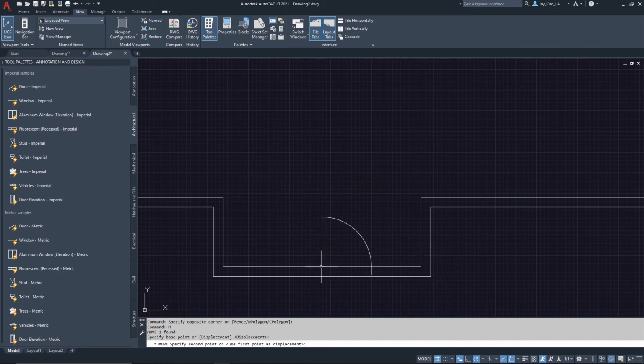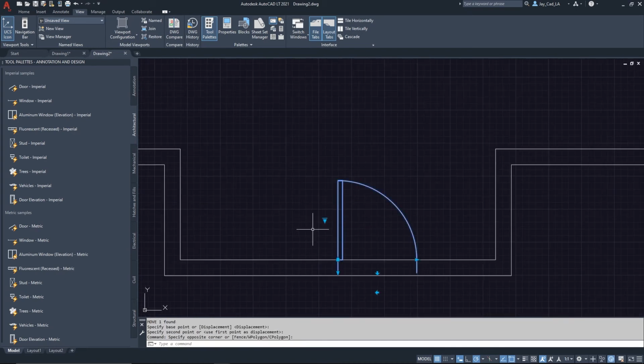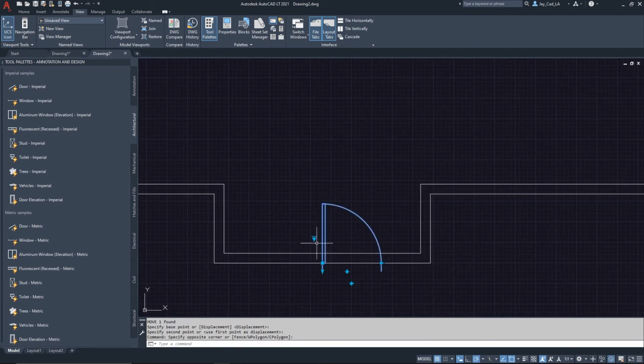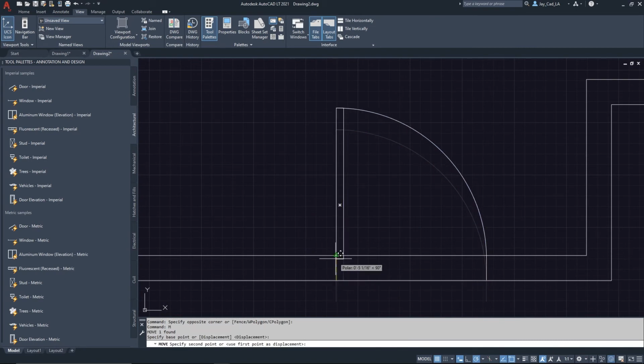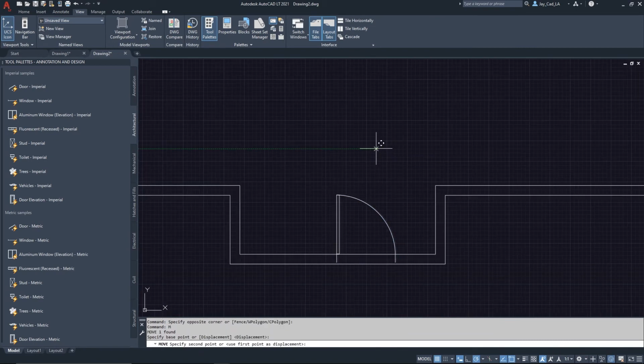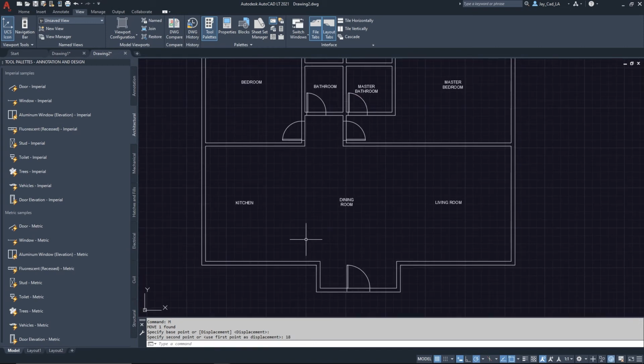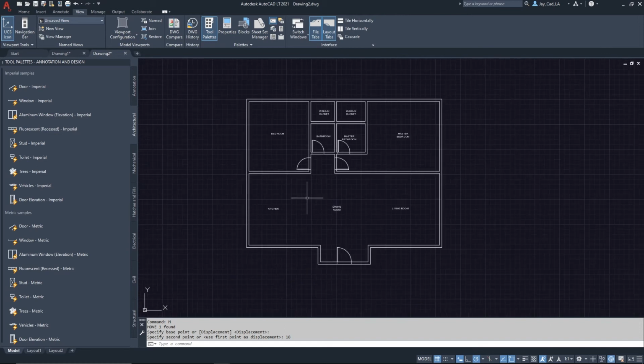Probably gonna have a double door here, or I'm gonna have a door and then we'll have windows on the sides of it. And then this door, I'll make it much bigger. I'll make it 3 feet, and then I'll move it here to the middle point. Let's move it back to the interior middle point, and then I'll move it to the left by 18 inches. That way it's exactly on the center. Okay, so now I've marked mostly all of the doors.